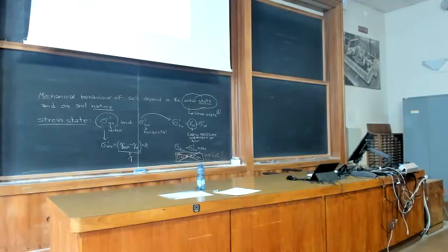Because the deposition of a soil deposit, or soil layer, is the result of the environment, but also the fact that the force acting on the grains is gravity. So the vertical stresses which act among soil particles are different from the horizontal ones. So packing of the particles is a function of the depositional conditions, as well as soil nature, physical properties, etc.